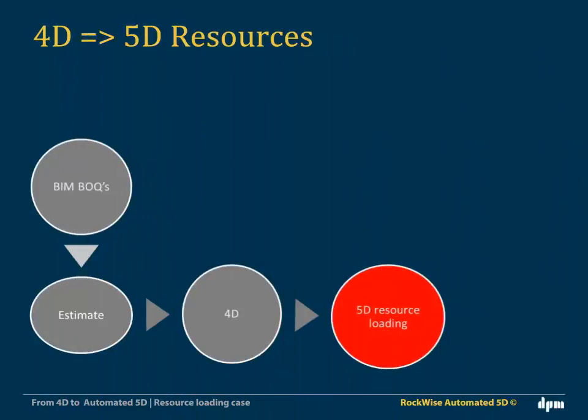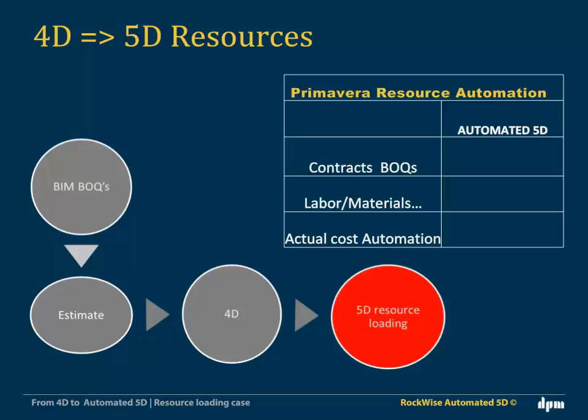After the automated generation of bills of quantities from BIM and their allocation to their proper contracts, an estimation for each contract and its BOQ resources is performed. Synchronously, the alignment between planning and BIM design should be done to reach an error-free 4D model. It is then where the automated engineering calculation of resources and their loading is performed.